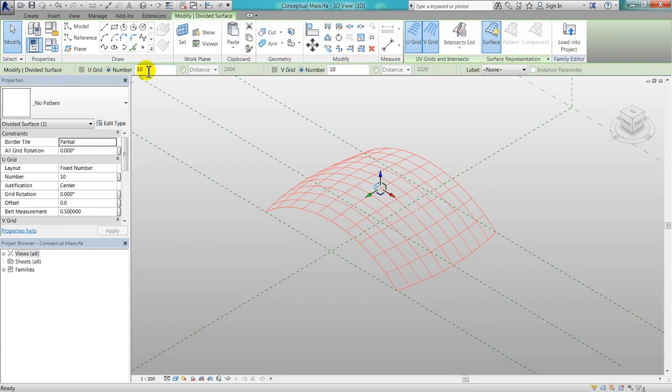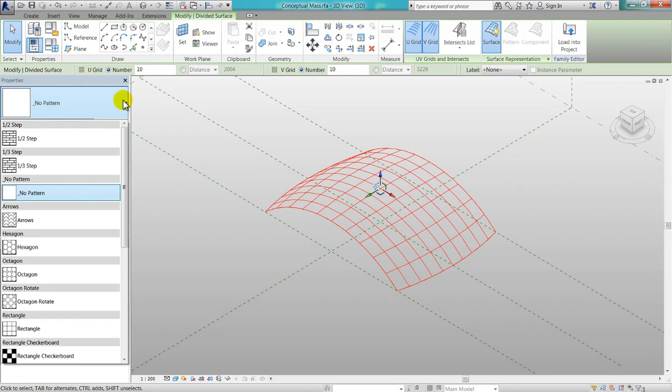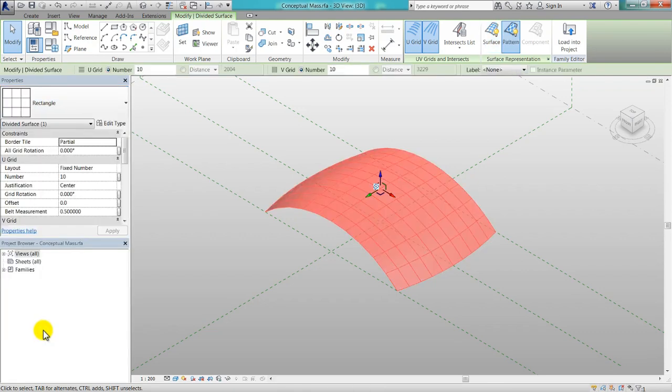Also, and this is a very important step, we need to define a pattern. In the type selector, choose Rectangle. The tool will automatically generate triangles from this setup later on anyway. Please note that when using the form simulation tool on 3D geometry, make sure that the mesh is consistent around the edges.